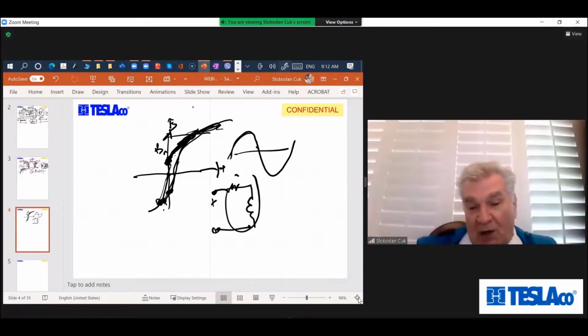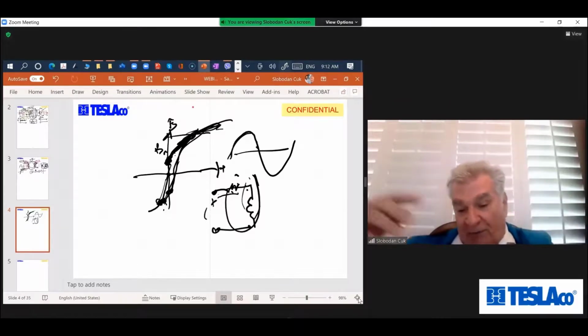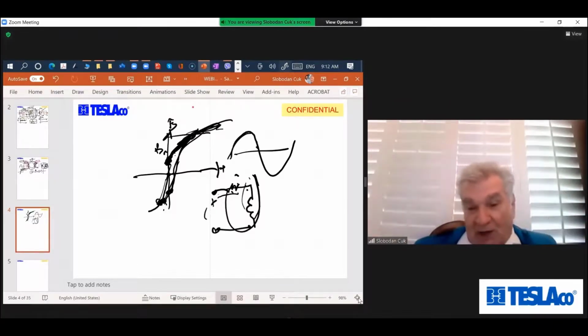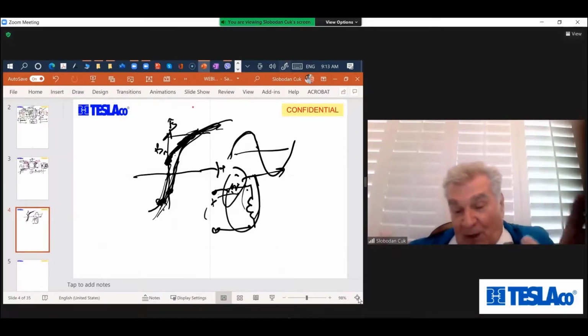So if you have too much voltage flux here, you'll draw the current, and this current will reduce the drive in the positive direction. So you see, it's self-correcting. Negative feedback essentially makes a core that may start with remnant magnetism eventually settle in a symmetrical way. So you would have a real problem if your transformer had zero resistance, right? Let's say it's made out of superconducting coils. Then there is no such thing, and it will definitely saturate.